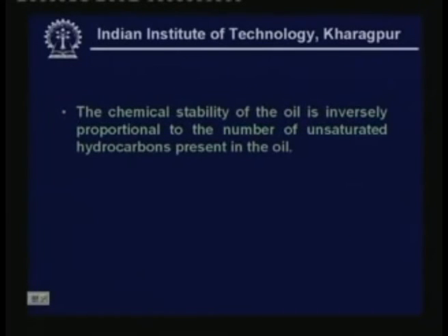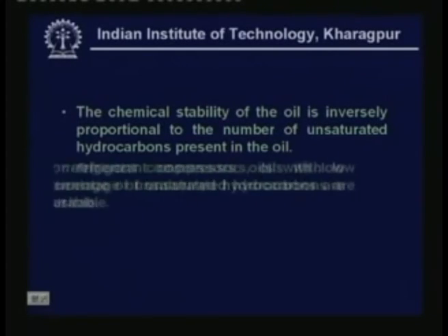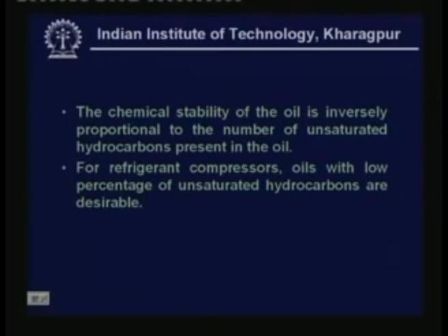So the chemical stability of the oil is inversely proportional to the number of unsaturated hydrocarbons present in the oil. That means higher the number of unsaturated hydrocarbons, smaller is the chemical stability. So for refrigerant compressors, oil with low percentage of unsaturated hydrocarbons are desirable.